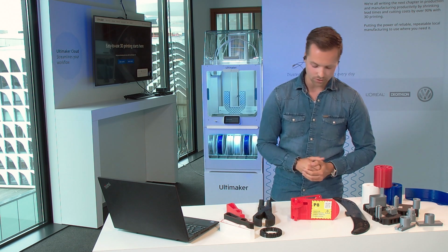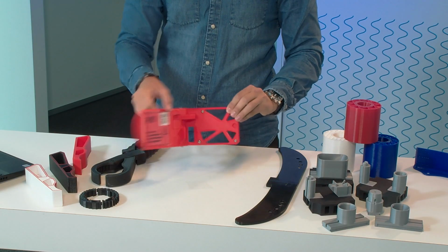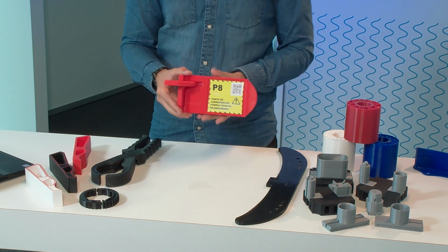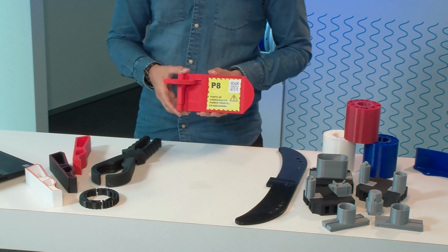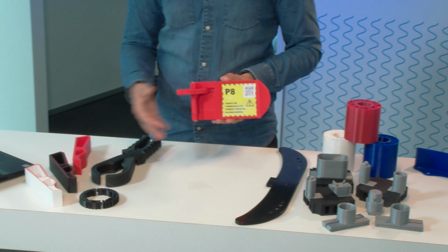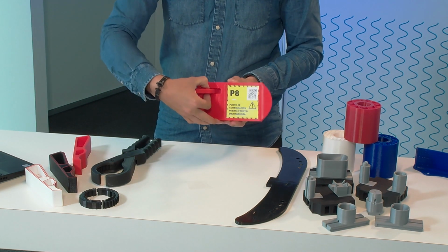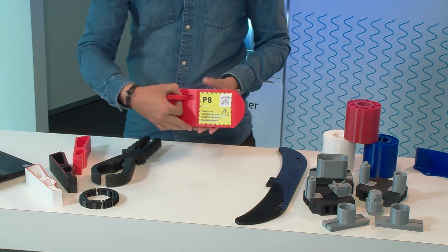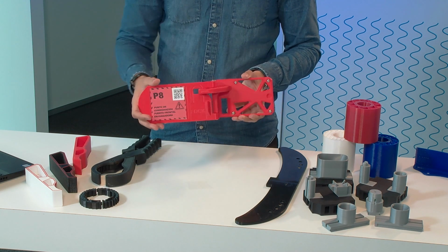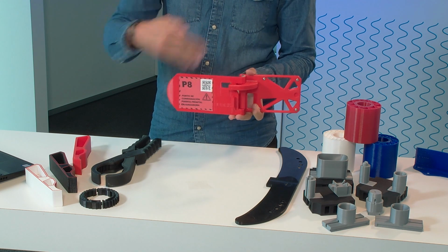I will just briefly demonstrate how it works. So basically it's a flap which you can rotate, and in a normal situation it is positioned on a machine like this. You will see that there is a yellow tag, also with a QR code, so operators can scan the instructions as well. There will be a padlock in here. There's a hole here, so people cannot put the LOTO system on when it's not needed. When it is needed, they unlock the padlock, they shield off the sensor, which is probably here in this location, so you have a sensor and a door.